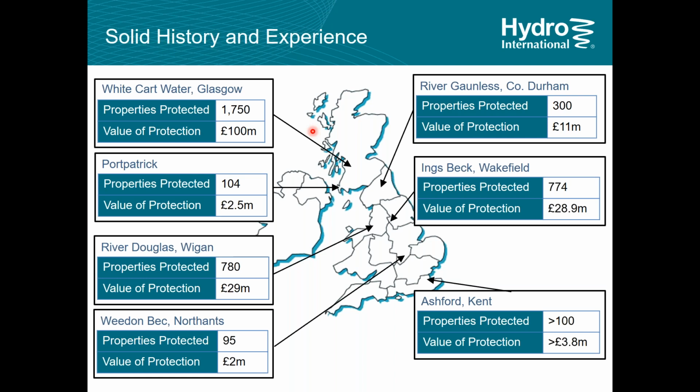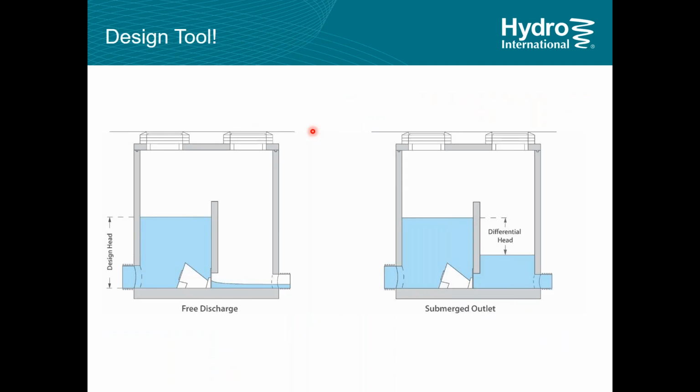and doing very well. The main advantage of the vortex valve for these flood control type dams is that they work without anyone, doesn't require any electricity, doesn't require any moving parts. There's no need to have a manual actuation. They just sit there and work. They're very robust.